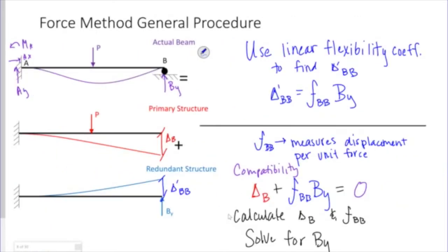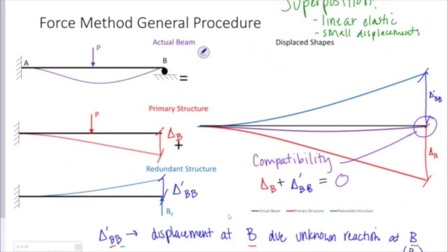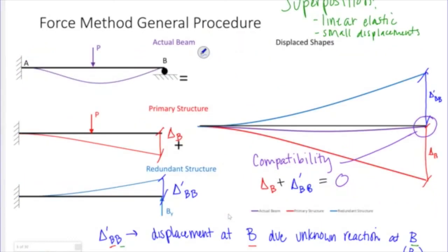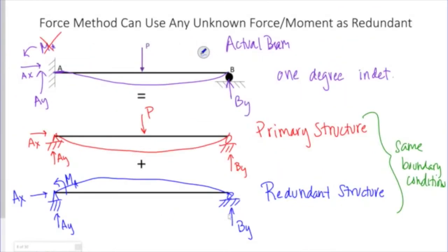So previously, I took out my vertical reaction at B and applied it as a concentrated load at B. Now I'm taking out my moment at A reaction and applying it as a concentrated moment at A for a pin end. Right? This becomes that.